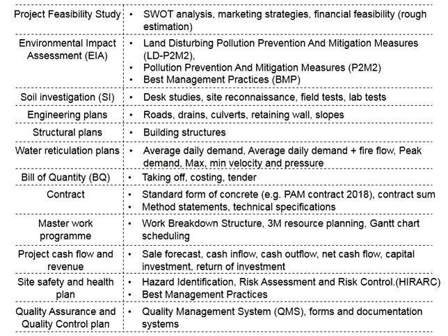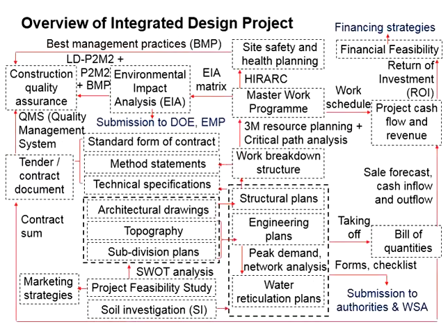There are also requirements in terms of the maximum and minimum velocity of the water flow in the water reticulation system. Especially, the velocity cannot be too slow, as that will encourage the deposition of sediments. All these plans need to be submitted to the local authorities as well as the water supply agency for review, evaluation, and approval. Therefore, it is important to check with their guidelines.